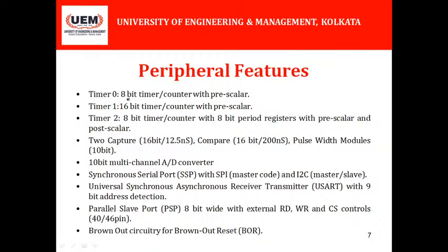Timer 0 size is 8-bit, timer 1 size is 16-bit, timer 2 size is 8-bit. Why is timer or counter written with a slash? Because both timing and counting operations are basically done by this unit. Timing operations, such as calculating the clock period, are an operation of the timer.